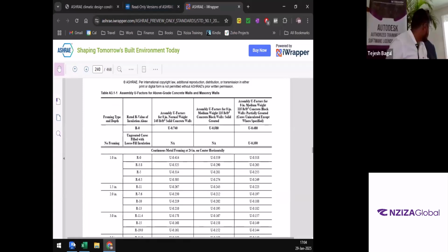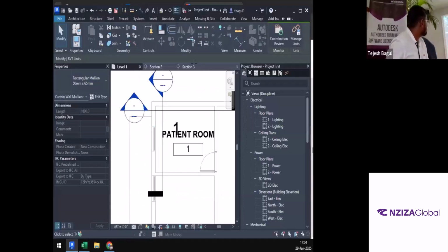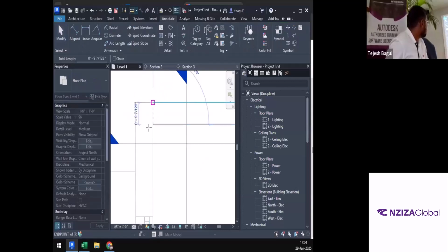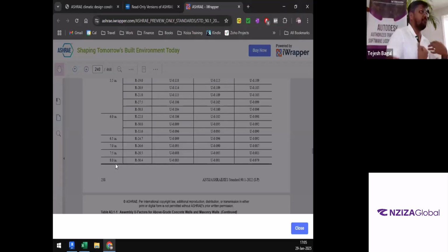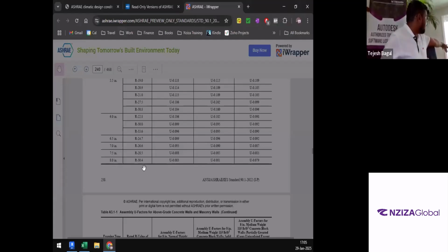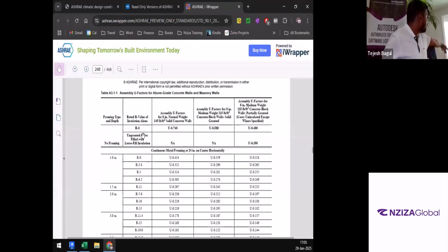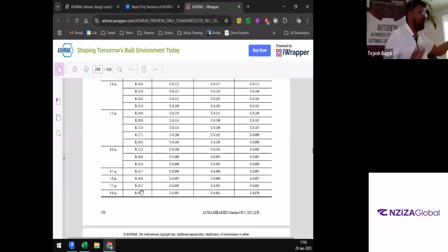Now over here, yesterday we checked the wall, how much was it? Something like 8 inches or 9 inches. Yeah, around 9 inches. But we had checked that we are only limited to 8 inch over here, which is fine. The greater the thickness of the wall, the better the thermal resistivity. It is always better to have 2 jackets if you are feeling cold than 1 jacket. So it is fine if we enter these values over here for no plaster on the outside. These are the R values that we are considering. The R value for an 8 inch thick wall is R 30.4.